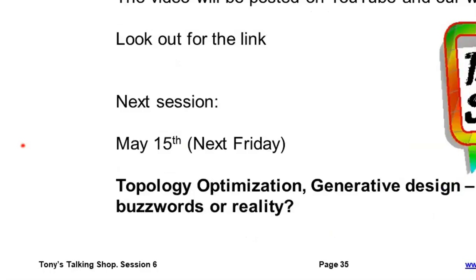Yes. There are some questions about last week, and then coming into this week, there's a question from David. It says, "Hi Tony, thanks very much for the presentation. Maybe I didn't catch it. In the stress life method, does the vertical axis S mean the stress amplitude?" Yes, it is the stress amplitude, so we can work with stresses coming straight from FE analysis.